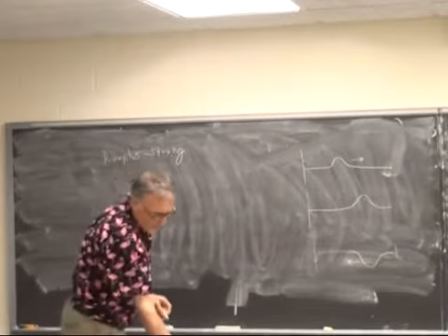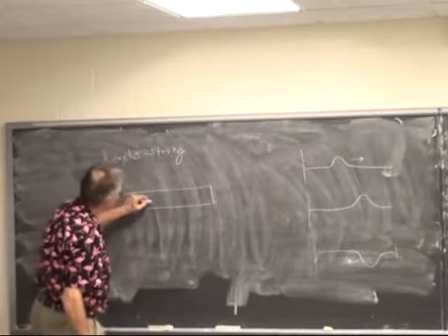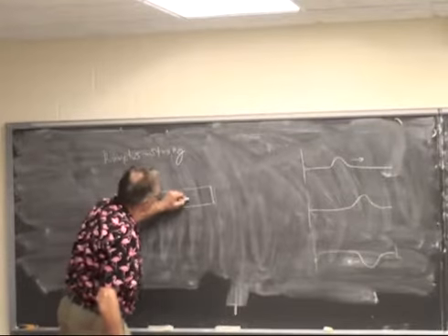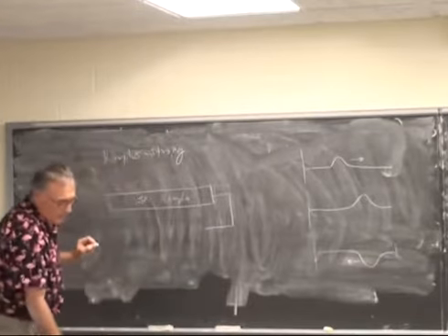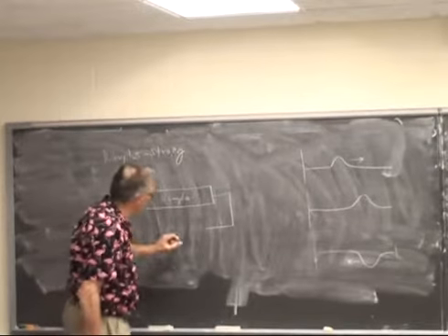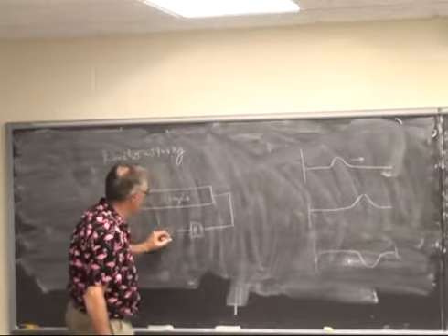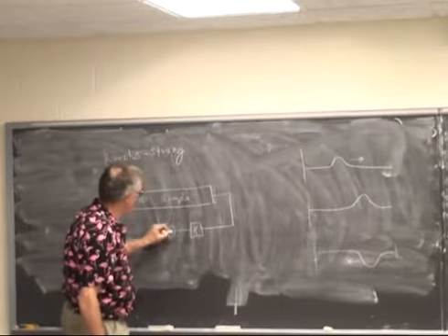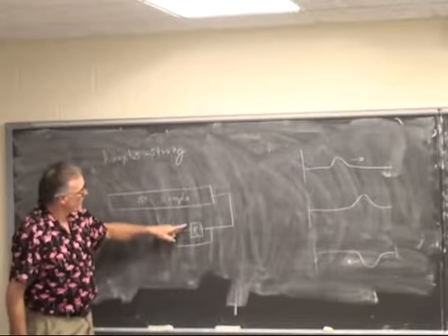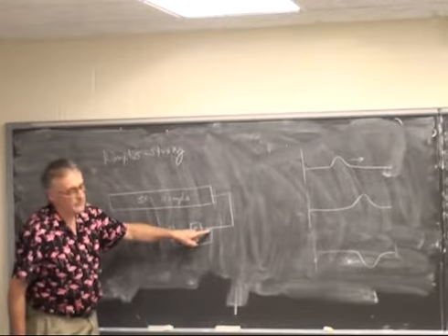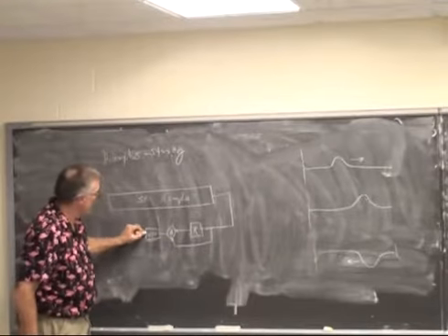And the specific form that they took was that you have a shift register that is n samples long, followed by a loss element which was of the form a one sample register with the one sample delayed version of the signal added to itself and then shifted by one and then fed back.